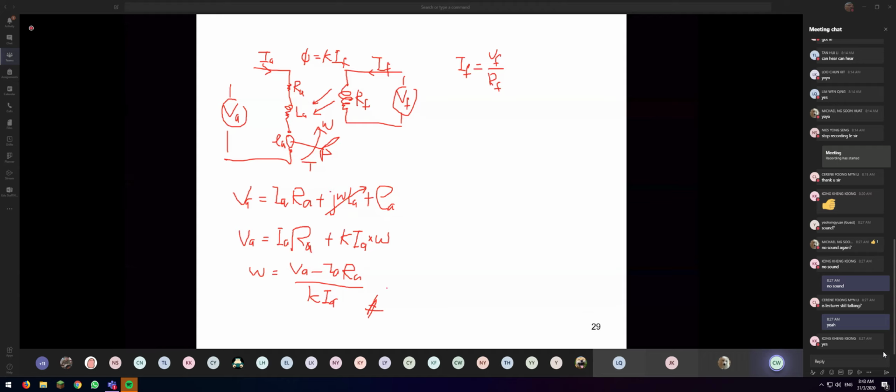So this is about the speed of the motor, and then the second one is the torque. Okay, for the previous permanent magnet DC motor, the flux is a fixed one. But if I replace it with the separately excited coil, right, the winding, now the torque can have much better control, which is equal to IF multiplied with the IA.